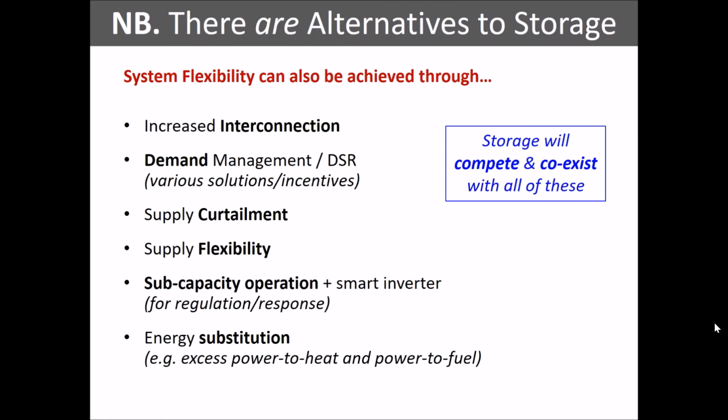On a distribution level, again, same issue. If you've got too much solar generation on rooftops and it's still trying to push it back into the grid at one time, that particular example is a bit more relevant to what you mentioned about voltage fluctuations, reactive power, and so on. I'm not going to go into reactive power now, but some of it is about peak transfer capacity, and some of it is about instantaneous balances. That's where the reactive power thing comes in. I probably didn't explain that terribly well.